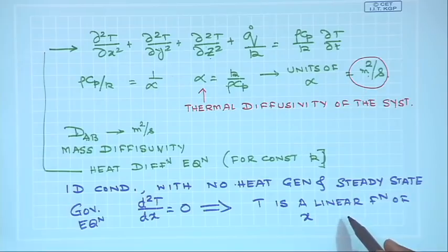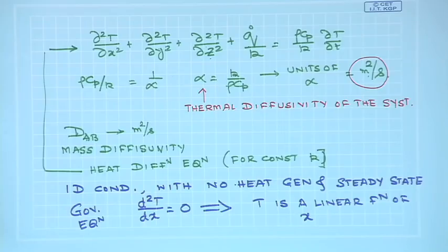temperature inside the system. The same type of equation can also be derived for the case of cylindrical systems and spherical systems. In cylindrical systems the temperature can be a function of radial location r, theta or axial location z. So, t is going to be a function of r, theta and z, and in the case of spherical systems the t can be a function of r, theta and phi.